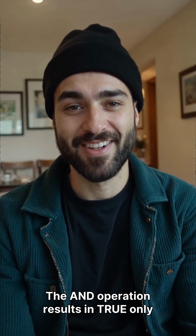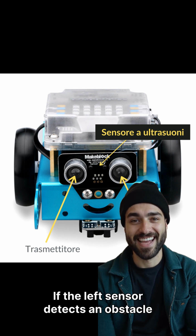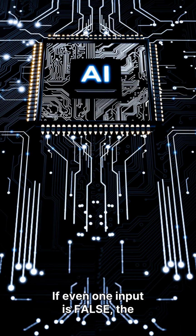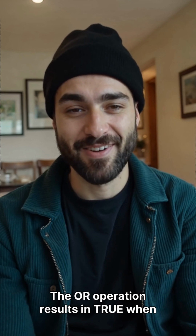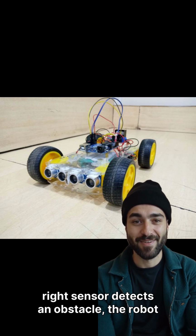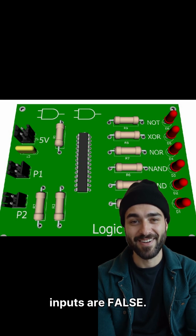The AND operation results in true only when all inputs are true. If the left sensor detects an obstacle and the right sensor detects an obstacle, then the robot stops. If even one input is false, the result becomes false. The OR operation results in true when at least one input is true. If either the left sensor or the right sensor detects an obstacle, the robot turns. The output becomes false only when all inputs are false.